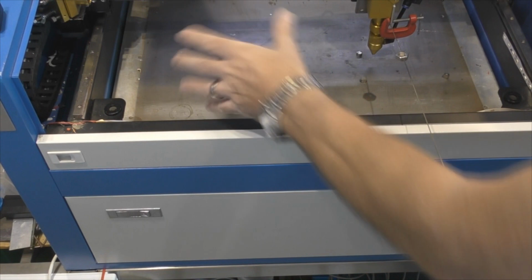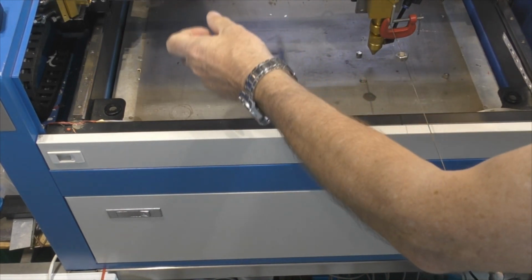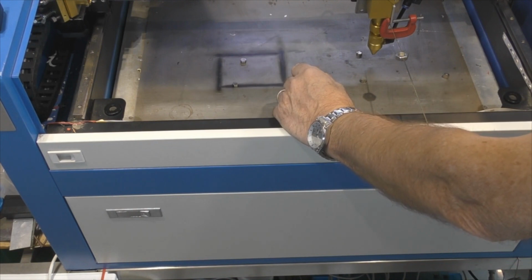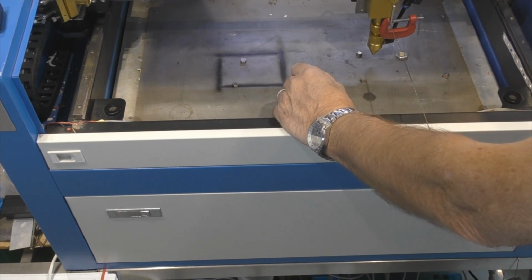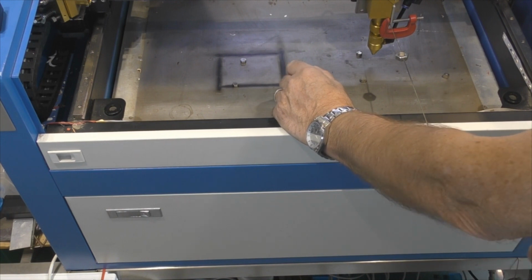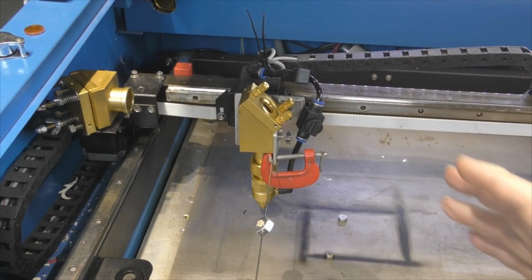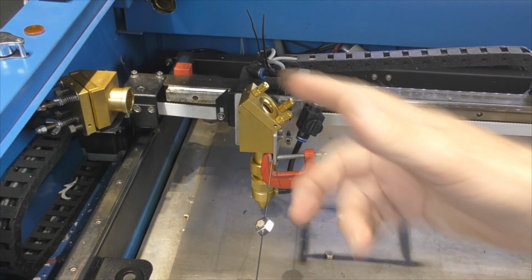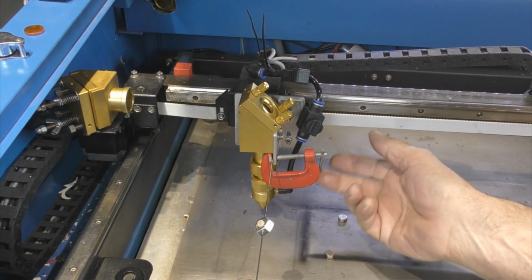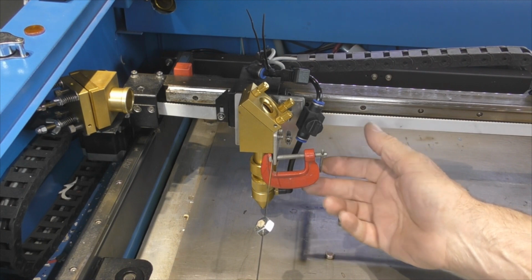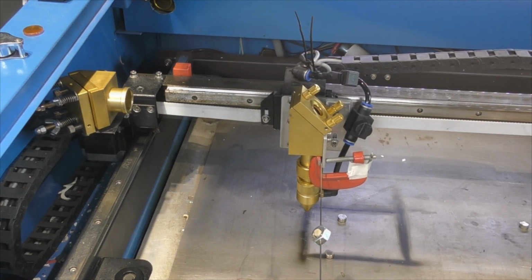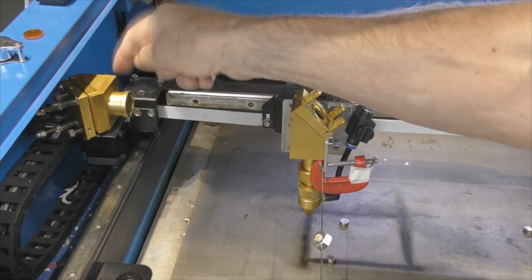3 sound phases. We've got this very strange and vibratory sound up to about 40 millimeters a second, and then the stepper motor changes to a much smoother sound from 50 millimeters a second upwards through 70. I can hear some of the more seasoned engineers amongst you saying, yeah, but that vibration's not from the stepper motor, that's from this loose bit here. That's going into resonance. What do we think now? The sound is emanating from that stepper motor just there.